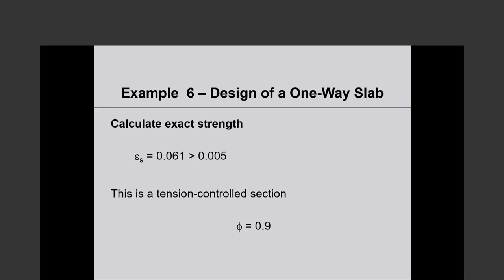So the slab in monolithic construction, part of the slab acts together with the beam. Your beam is the physical beam plus the overhanging flanges on the two sides, and this is not conditional.